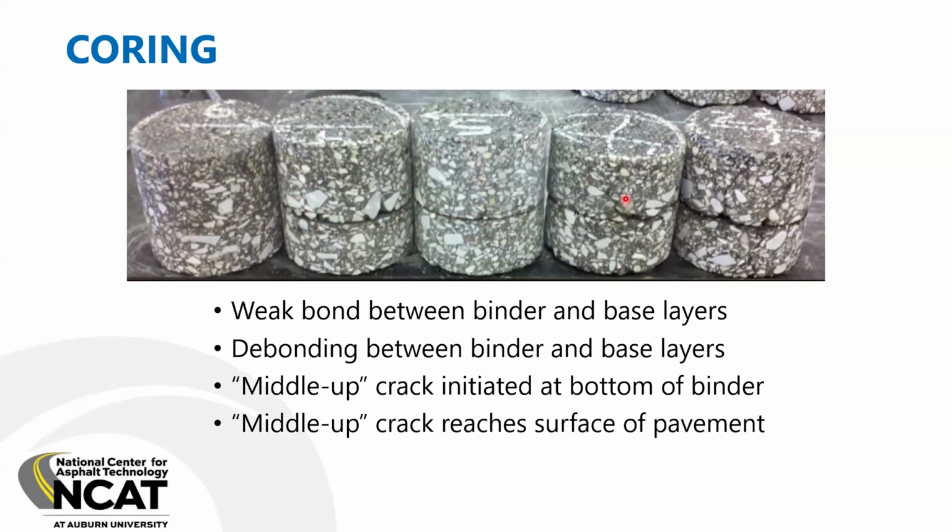And so in this fourth core, that middle up crack has proceeded all the way to the top, and you can see how it's marked here on the top. So this was actually visible before we pulled the core, one reason we pulled this core in this particular location.